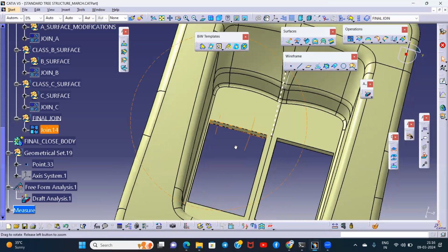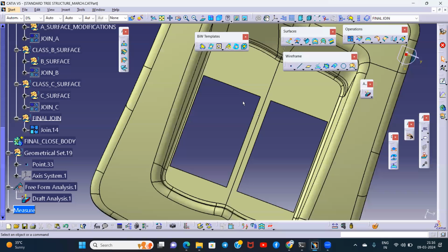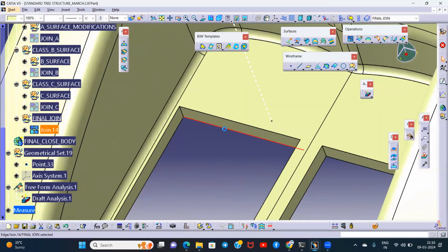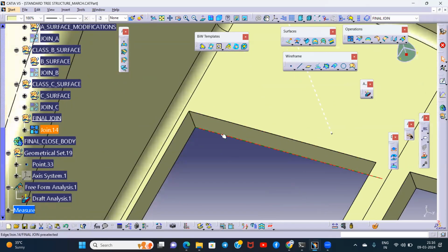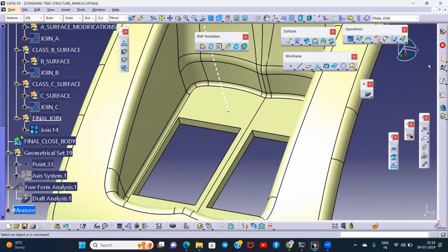So the general rule is, if I normal the tooling direction from the viewer's point, okay, then the parting line we are keeping onto the B side, because on the A side the parting line will be visible to the customer or the viewer, right? So we have to hide the parting line. That's why I need to shift the parting line here. So this surface I need to clear into the cavity side. And if I am clearing this surface into the cavity side, then this surface draft will be 3 degree. Then this will be green and this will be green. Both are green.